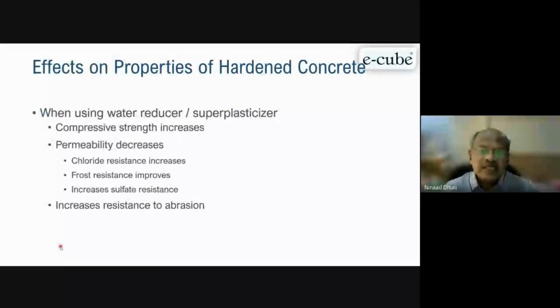Though we are saying that crushed stone sand is an inert material, not reacting with anything, it acts as a filler. But when they are producing this sand at the quarry end, a lot of clay material or overburden clay may mix with the fine aggregate. Now this clay is responsible for the response to your admixtures.